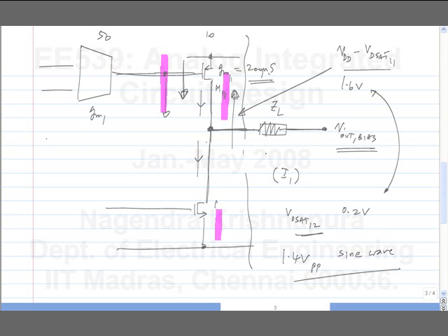So it's 700 millivolts peak divided by 5 kilo ohms. That is 140 microamps. So you need at least 140 microamps. You can expect currents of the order of 150 to 200 microamps in the output stage to be able to accommodate this. So clearly, if the load resistance decreases and you have to support the same swing, you have to use more bias current, obviously, right?